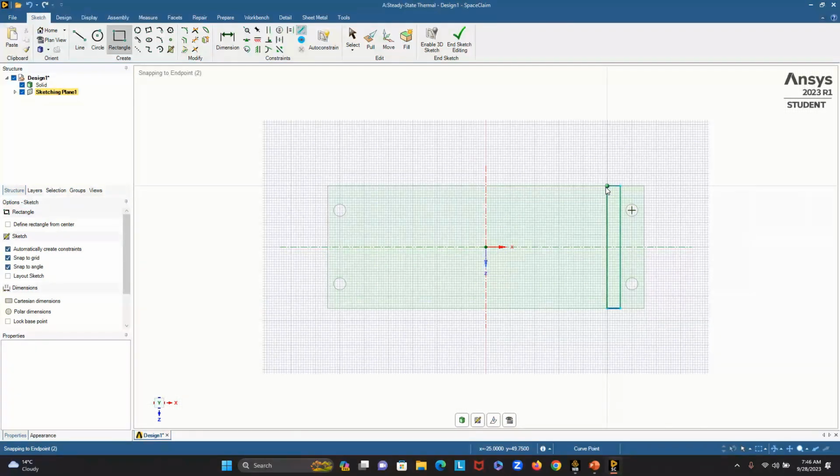As we haven't calculated the gap in our class, let's just draw the regular 11 fins one, so that we can keep it simple, and after that we can also try the 5 fins one. So the length will be 50 mm, and the gap will be 5 mm. So I drew my one fins and one gap already.